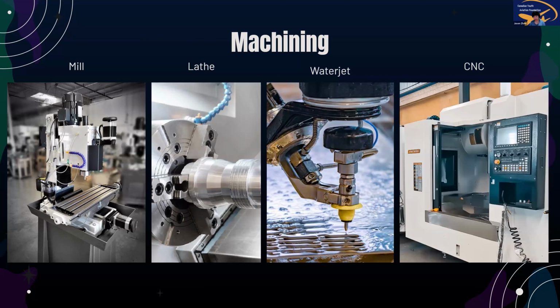Something else you could use is called a water jet. How a water jet works is that this jet sprays water at speeds faster than sound, which creates a laser of water that can cut through an inch of steel. Over here, you see little cuts being made by a water jet. A water jet is great for making 2D cuts in a big plane of material, and it's really, really quick.